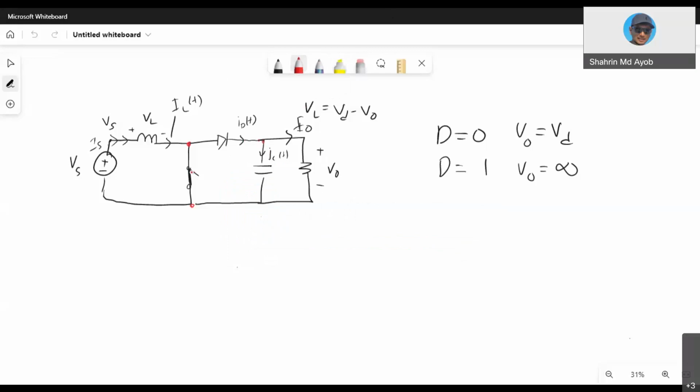Okay, when the switch is on, the diode is off, right? So the current during the on state is 0. Let me write it down. It's actually 0. There is no current. But when the switch is off, the diode will turn on, right? And then your IL will flow through the diode. So we know that IL at the on state is...